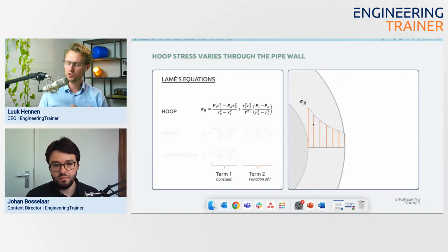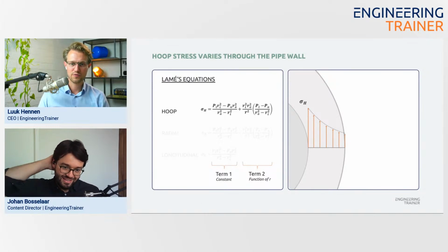And technically that would also mean that if you would bring the stress up to the limit, so reaching, let's say, the proportionality limit or yield stress, you could have some yielding all the way at the inner side of the wall. I mean, that's just a thought, but this is basically the limiting element. I guess that's something to take away here. It's interesting. All right, let's move ahead.